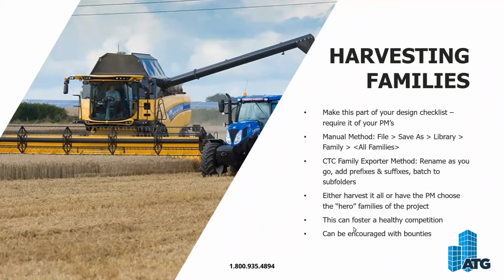There is another way to help automate this. CTC has a family exporter tool. It's kind of similar, except it gives you a couple of other bells and whistles. It's also a free tool as well. So you can get the BIM batch suite that it comes in, and this tool is going to remain free for you. But it allows you to basically name things as you go, to have it subfolder and put content into other subfolders as it goes.